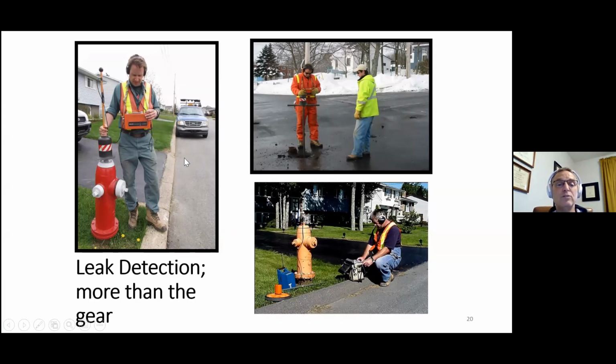But over time, you get used to hearing different sounds from different types of pipes, everything from ductile to cast iron to asbestos cement to pre-stressed concrete cylinder pipe, and even, yes, PVC. But PVC is very difficult for leak detection because you do not get much sound attenuation. But ductile and cast iron, you'll absolutely find leaks pretty easily with this technique. So we can listen on hydrants. Sometimes the hydrant branch itself might be leaking, but we'll listen on all our hydrants, and we can zero in on an area where we know we've got leakage.